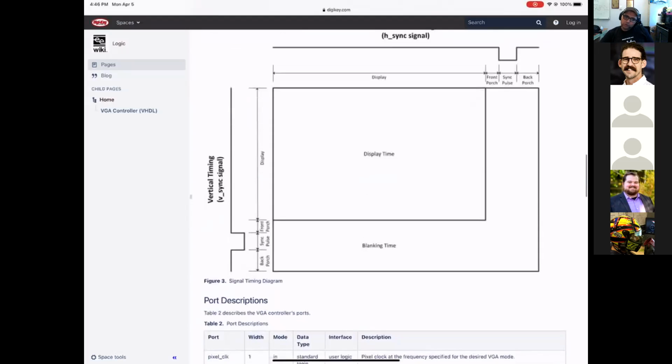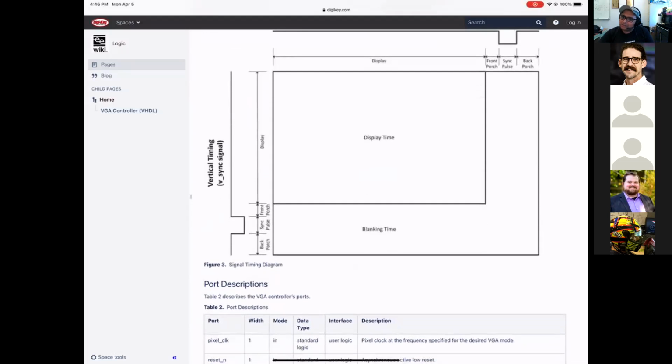If you look at the vertical, it has the same thing. Have you noticed? It has the back porch. It has the sync pulse, which goes low, and then turns back to the front porch. What is the best way to implement this? Somebody can tell me. Counters. You guys agree? Yeah. So my question, so far for everybody, does it make sense what I'm saying?